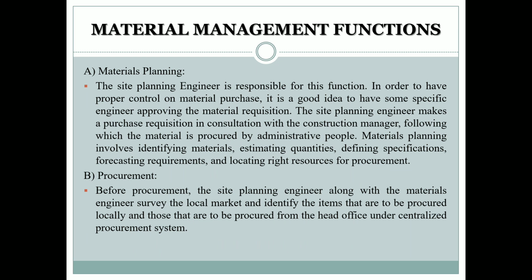So what are the different material management functions? The first one is material planning. The site planning engineer is responsible for this function. In order to have proper control on material purchase, it is a good idea to have a specific engineer approving the material requisition. The site planning engineer makes a purchase requisition in consultation with the construction manager, following which the material is procured by administrative people.